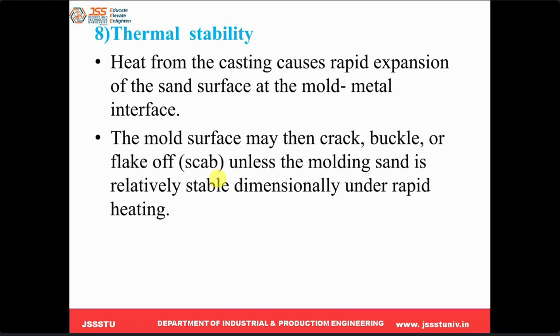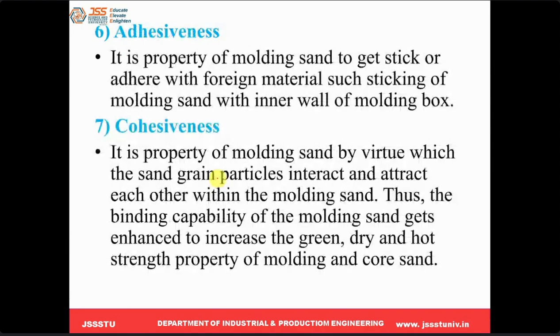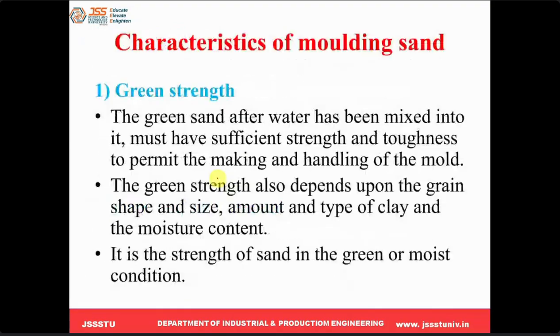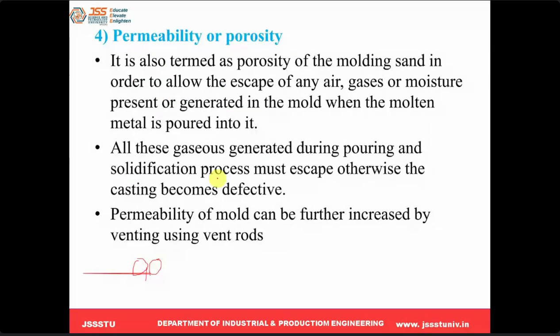It will be stable in nature even when exposed to higher temperature. So these are the minimum properties any molding sand requires: thermal stability, cohesiveness, adhesiveness, refractoriness, permeability, flowability, dry strength and green strength.